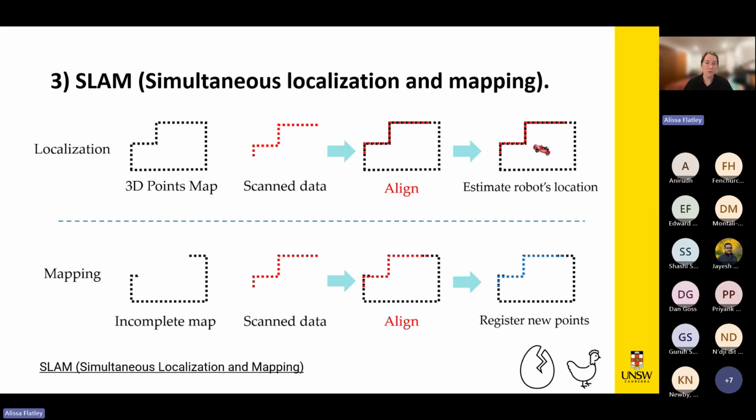So autonomous navigation requires locating the machine in an environment while simultaneously generating a map of that environment. It's quite difficult to accomplish because the machine needs to have a map of its environment to estimate its location. But to generate a map, it needs to know its own location. So this is why it's sort of a never-ending circle of dependency.